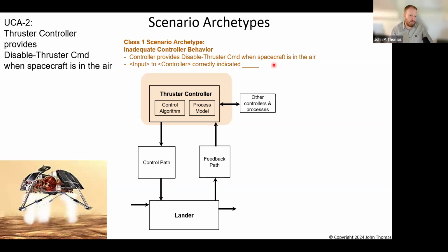And it turns out there are some other inputs that potentially could confuse the computer. There was actually a radar altimeter that the computer was looking at in addition to the footpad sensors. And there may be some way the altimeter feeds bad information, even though the footpad sensors work. The altimeter may feed some information that causes the computer to override and disable the thrusters anyway. And there may be a bunch of other cases to think through. But that's interesting, right? Anyway, do you see the pattern?